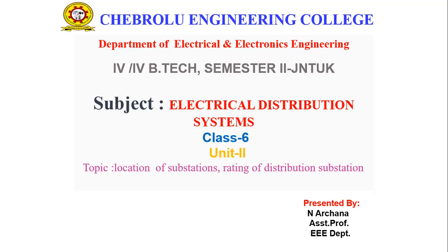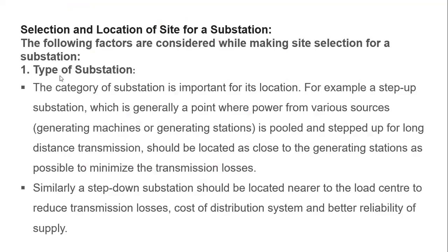Okay, the voltage levels and voltage regulation considerations, sub-transmission cost and substation cost, the cost of the primary feeders, mains and distribution transformers dictate the locations of the substations. Okay, the distribution transformers, feeders and substation cost and the land cost, that all will be considered for the location of the substations. For the substations, the following rules should be considered.